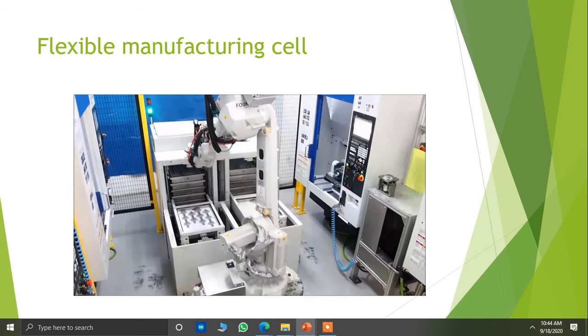For example, you have given 10 programs for 10 parts to the CNC machine. The CNC machine will execute one after the other in a sequential manner. But the robot has to place the parts according to your program sequence. So your program sequence has to be handled in such a way that the robot also understands the program and feeds the appropriate raw material into the CNC machine. Clear?